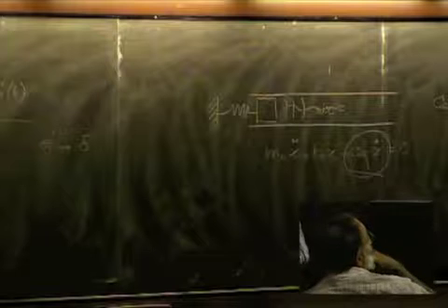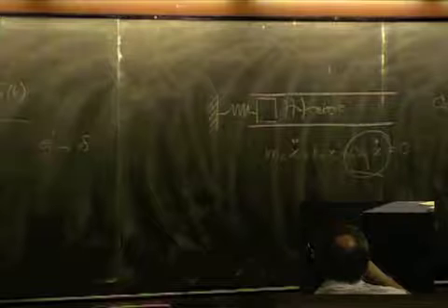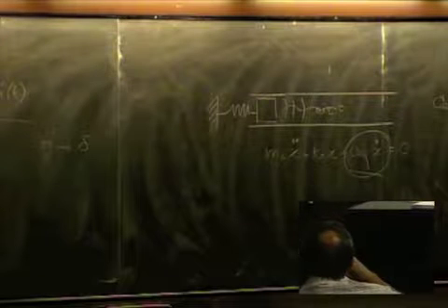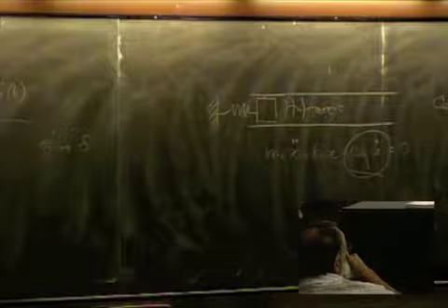Could you explain how, in your example, what would be G? How do you get it from this integral? Oh, well, it takes some time, but the concept is very easy. You have just to compute the impedance of the system that is connected to the one degree of freedom system. Then you compute the impedance, and then you compute the inverse Laplace transform of the impedance.